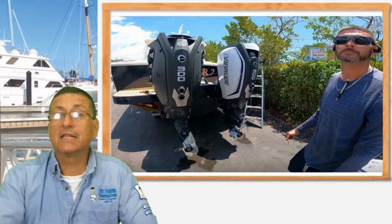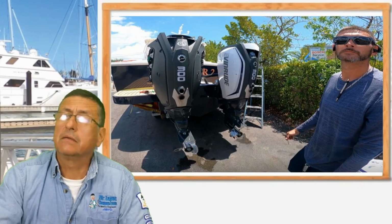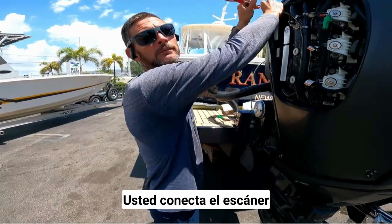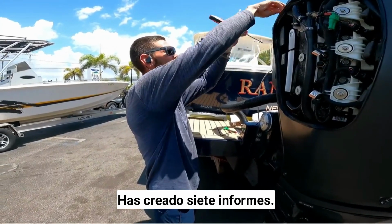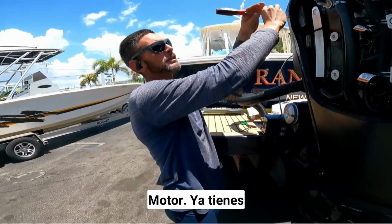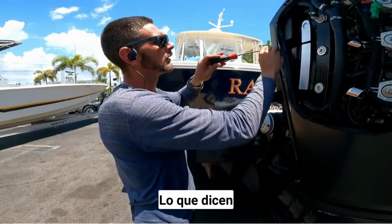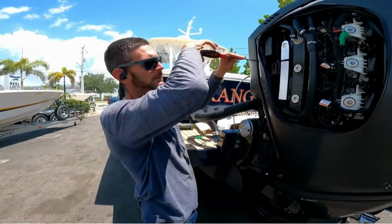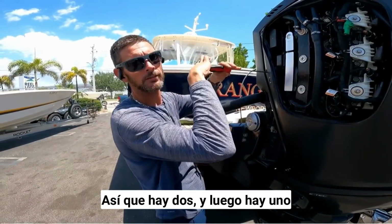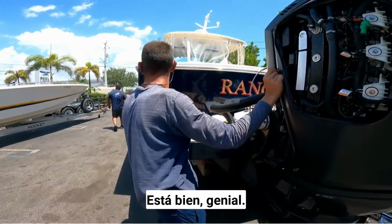After that, Danny connects the computer, the scanner, and he identifies some errors, some codes. How many codes, Danny? In different modules. You connected the scanner and you found 7 reports. I downloaded all 7 reports. You've got an engine report for each engine, a control box report, and what they call the surface mode controller, which is what controls the joystick. There are 2 of those, then there's a pressure sensor module, plus the joystick assembly.